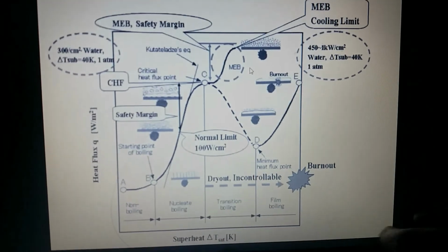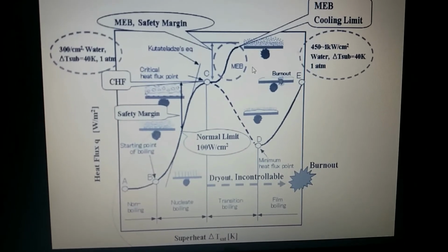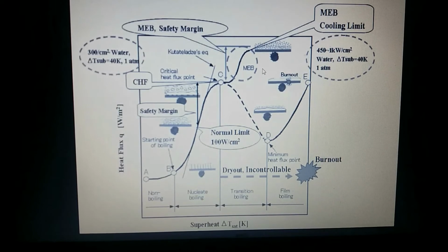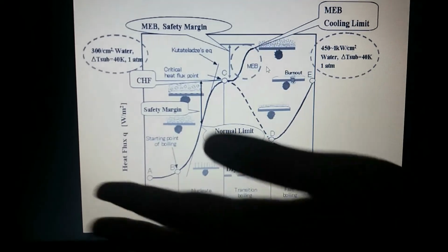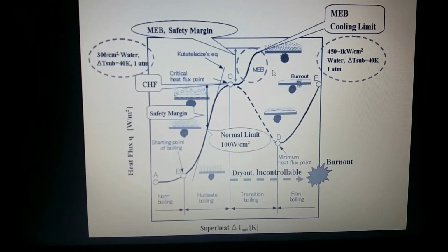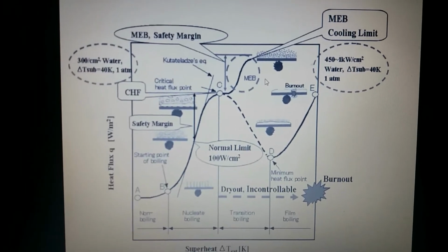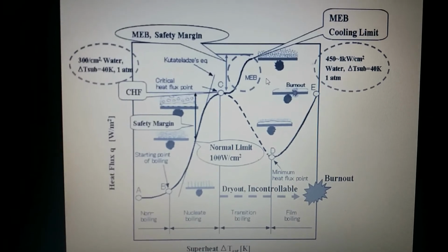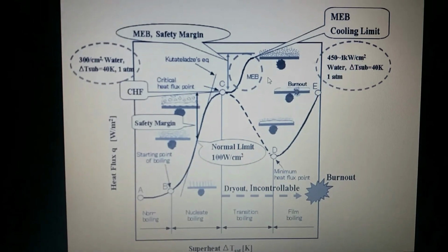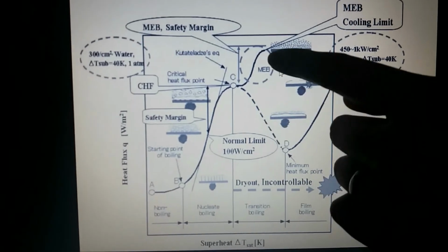So this is the diagram that is involved in the power electronic industry. The remaining liquid layer here, or micro layer below the coalescing bubbles around here, evaporates rapidly and the surface begins to dry. The boiling then turns rapidly to film boiling with the instant temperature rising through the transition boiling. Finally, the surface is seriously damaged by the high temperature.